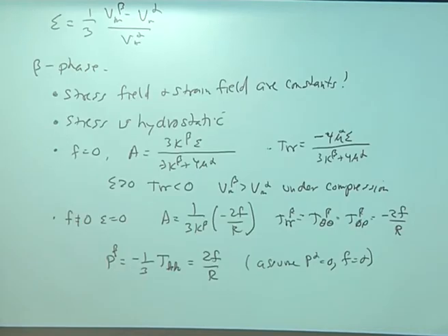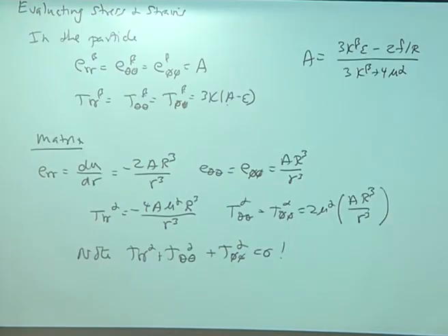So the other thing I want to point out is, there is a particular particle size so that these two will cancel. They cancel with the right sign of the surface stress. Then you have a stress-free system. So if epsilon is positive and your surface stress is positive, if you can find an R where that happens, that system will just stay there.